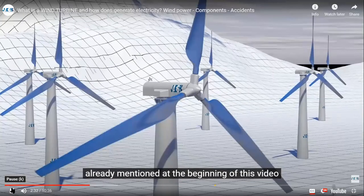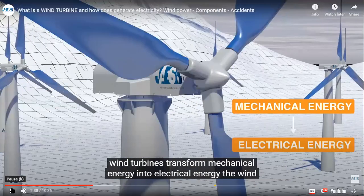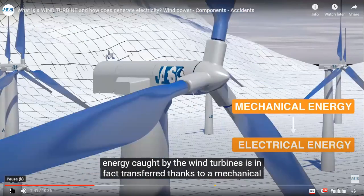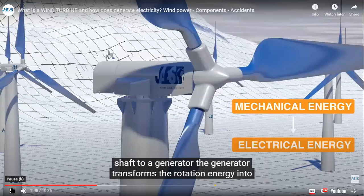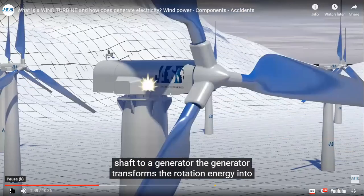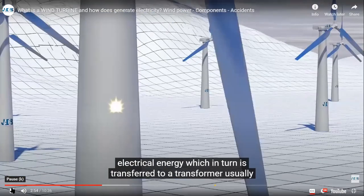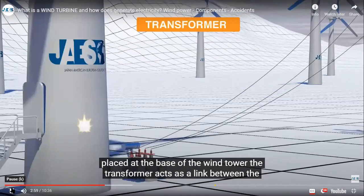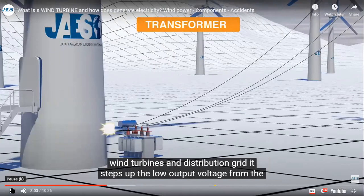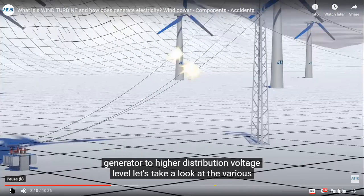As we already mentioned at the beginning of this video, wind turbines transform mechanical energy into electrical energy. The wind energy caught by the wind turbines is in fact transferred thanks to a mechanical shaft to a generator. The generator transforms the rotation energy into electrical energy, which in turn is transferred to a transformer, usually placed at the base of the wind tower. The transformer acts as a link between the wind turbines and distribution grid. It steps up the low output voltage from the generator to higher distribution voltage level.